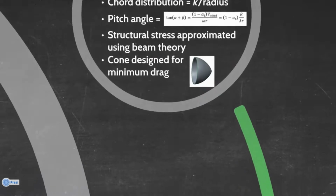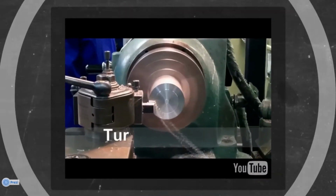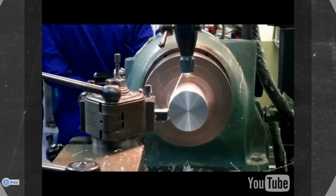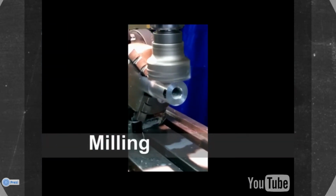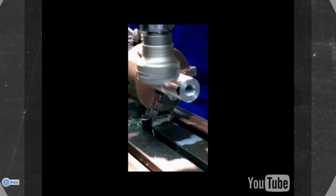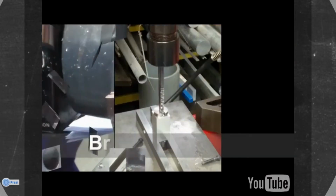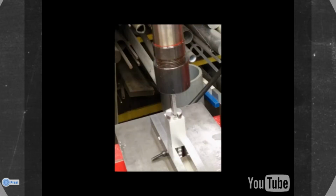The manufacturing process was split into 2 main parts, the hub, and the blades and cone. The first step in creating the hub was the turning process, where the lathe was used to produce a circular shape. Material was progressively removed as the aluminium block rotated. Then milling was performed so as to achieve the desired square shape of our hub. Following this, threading was done so that the cone could be firmly secured to the hub. The final step was to broach a keyway through the hub to ensure the wind turbine will be locked together with the test rig.